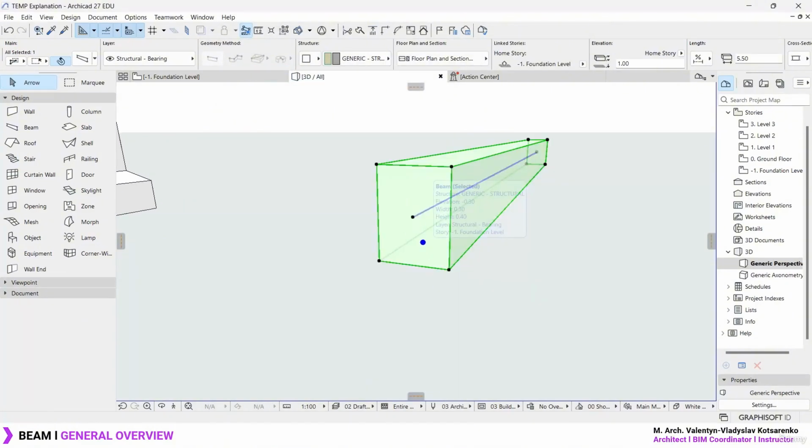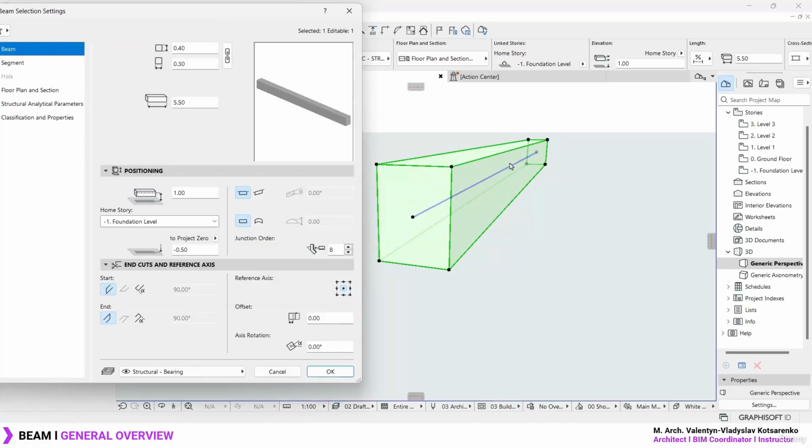Now, keep in mind, if you are an engineer who wants to calculate or analyze the structure for your project, this is something that you definitely want to keep an eye out, because for the analysis process that ArchiCAD uses, it will always keep in mind and consider these reference lines. So this is something you have to be on the lookout, especially if you're planning on analyzing the structure with more specialized tools or more specialized functions within ArchiCAD.